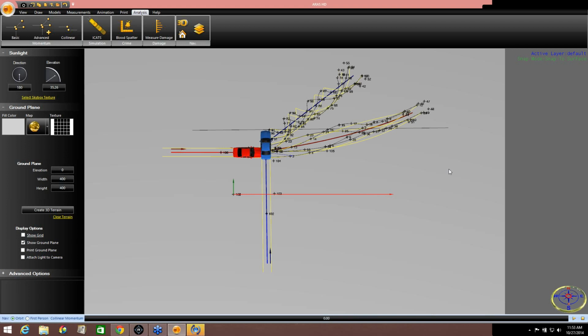If you see some black marks, a gap, black marks, a gap, black marks, a gap, well, you're going to have something less than 100%. If you see striations the whole time, then you probably don't have any braking. It's just scuffing. So it's just looking at your evidence in the road and determining what you have.